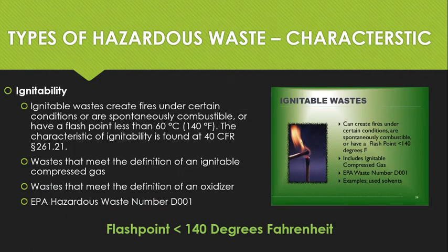So the first one, ignitability. Ignitable wastes create fires under certain conditions or are spontaneously combustible or have a flash point less than 140 degrees Fahrenheit. So that's the biggest thing, is if you're ever looking at an SDS and you see it says flash point and it's like 100 or 120 or 65, then you know that that's an ignitable hazardous waste.